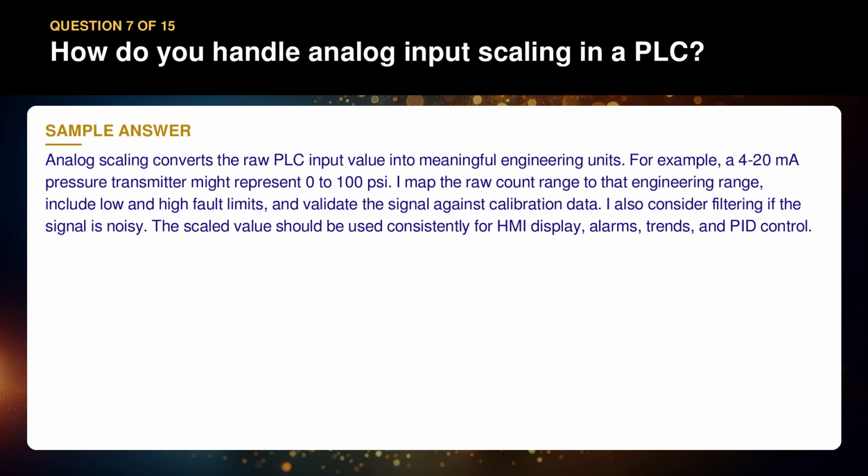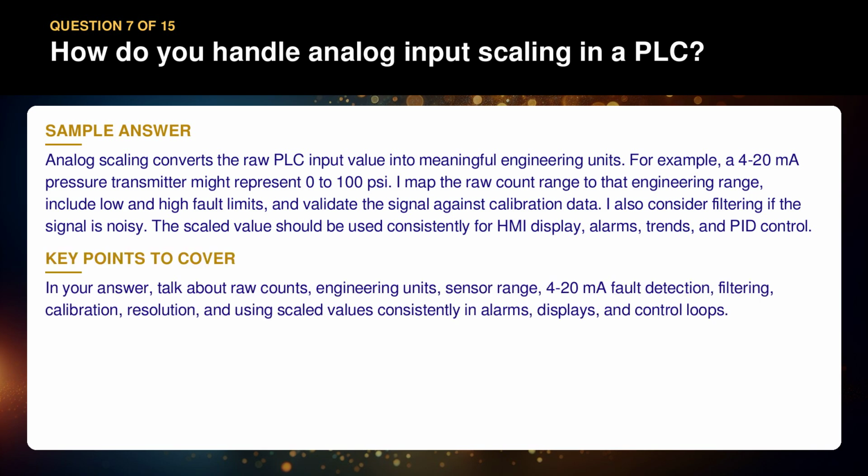The scaled value should be used consistently for HMI display, alarms, trends, and PID control. In your answer, talk about raw counts, engineering units, sensor range, 4 to 20 mA fault detection, filtering, calibration, resolution, and using scaled values consistently in alarms, displays, and control loops.